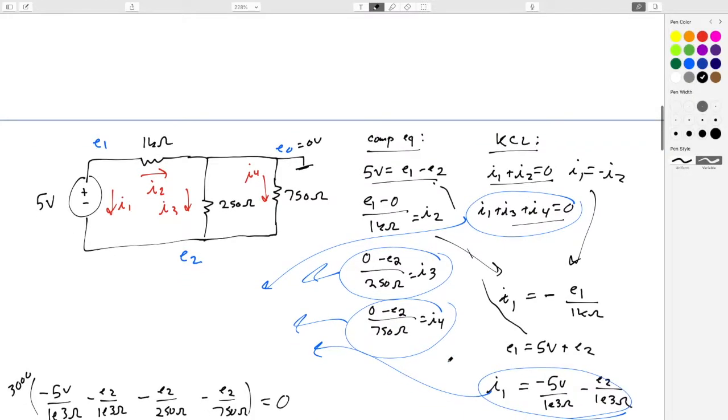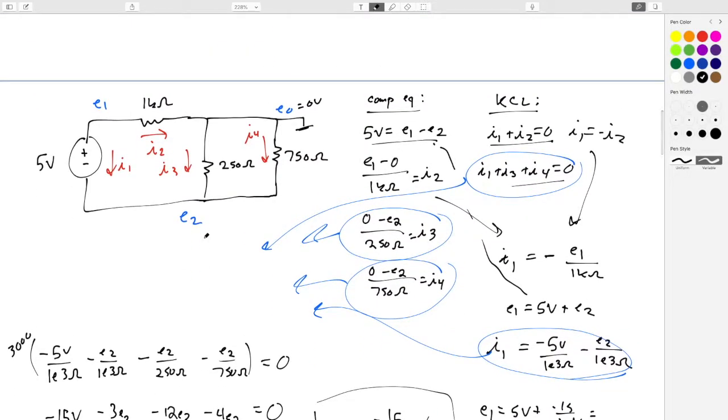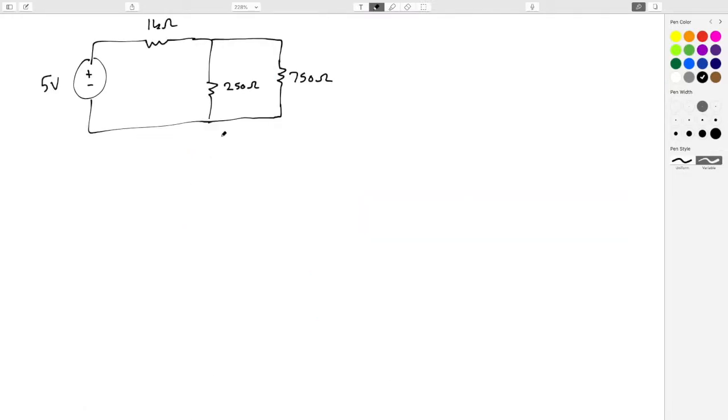The weird thing maybe for this one is, we called this 0, and all of a sudden E2, the voltage down here, is negative. But that makes sense, right? Because this voltage, whatever it is, is going to have a higher potential than whatever the voltage here is. Current is flowing from here to here. We know this from solving it. Current will flow from a region of high potential energy to a region of low potential, and we're seeing that happen.